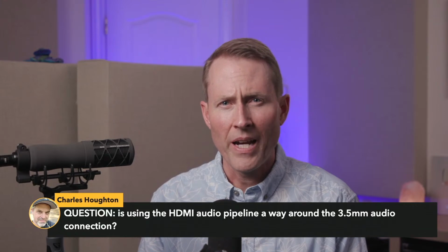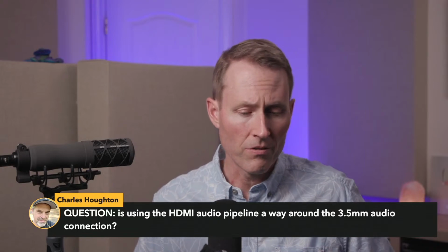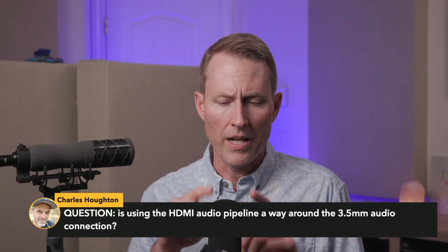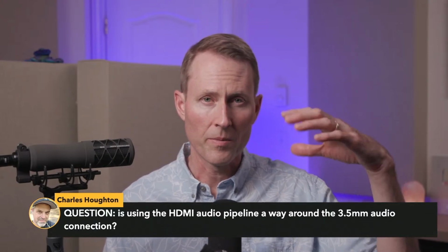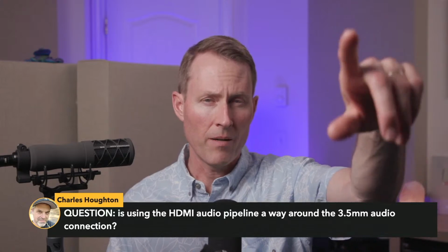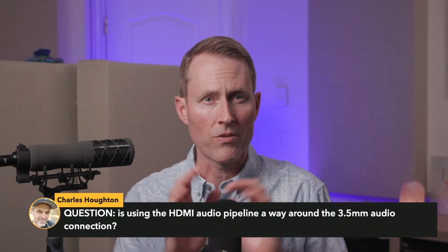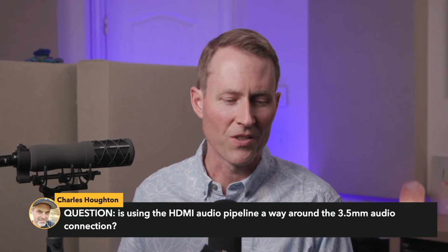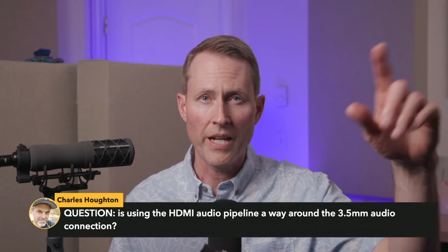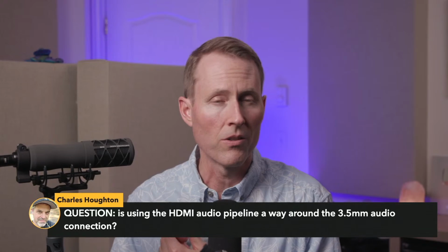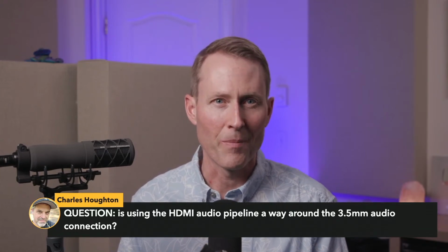Question: is using the HDMI audio pipeline a way around the 3.5 millimeter audio connection? And the answer is yes. For example, what you're hearing right now, I have this going into a channel strip that does the amplification and a little bit of compression, and then it sends it to the camera, which then combines it with the video and sends it via HDMI into the ATEM Mini. So yes, you can completely bypass all of this other stuff. If you're trying to get a mixer, you could run a mixer into your camera, and then that'll be carried forward via HDMI. There are lots and lots of ways to do this. So lots of things to consider there, lots of options. Thanks, Charles.